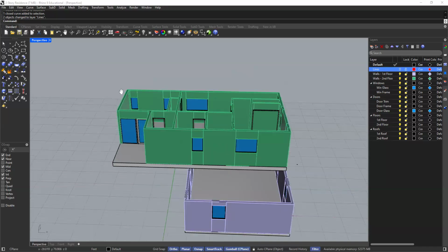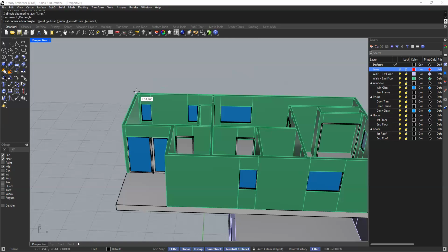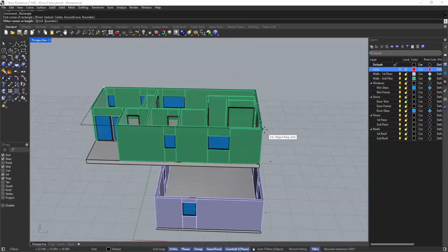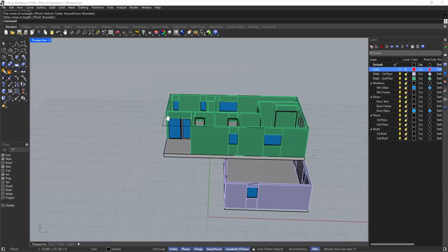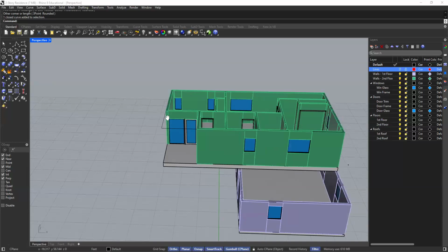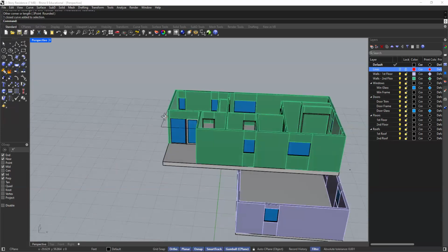The way we're going to do this is we're going to start off by drawing a rectangle, which will act as kind of like the base. And then we have to figure out, do we want an overhang? And if so, how far out do we want to overhang past the exterior? Typically it's about 1 to 2 feet. You technically by code don't need an overhang. There's ways of detailing it so that you don't have an overhang.